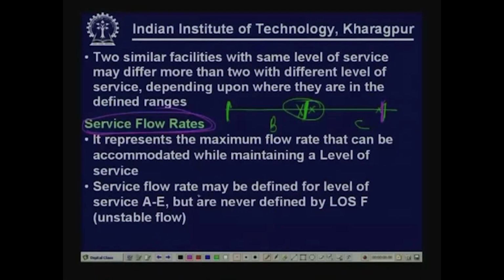So, service flow rates may be defined for levels of service A to E, but service flow rates are not defined for LOS F. The reason is obvious, because LOS F represents unstable flow operation or forced flow operation. So, you cannot really define the maximum service volumes with respect to LOS F.